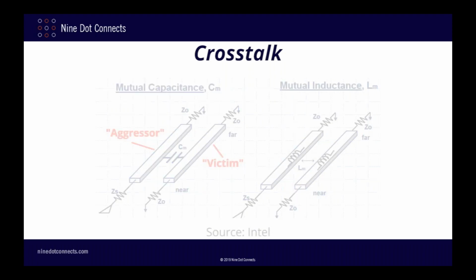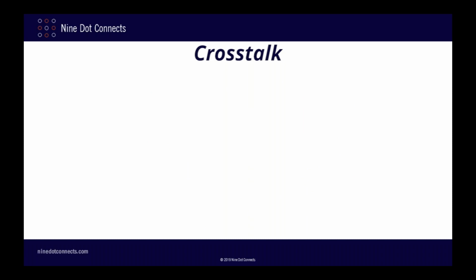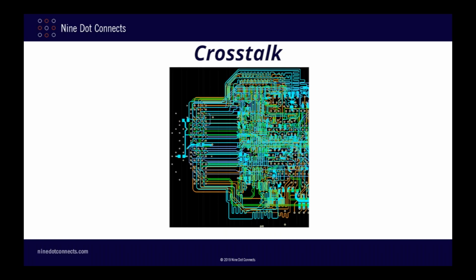Okay, let's dive right in and look at some simulations, which I'll then use to demonstrate various causes and remedies for crosstalk noise. Since crosstalk noise is caused by overlapping fields, it makes sense that having long parallel traces close to each other would be something to avoid. And as we see in my existing design, I do have a fair number of parallel traces for all of the signal groups. You might think this would cause excessive noise, but since we've seen the resulting simulation data and know for a fact that the board works, it seems like these parallel segments are not failing the design.